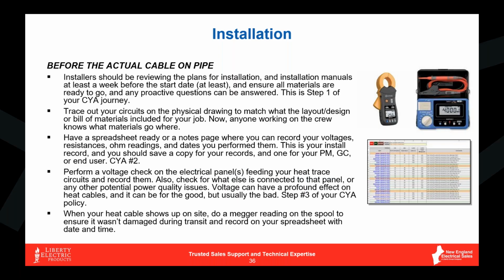You definitely want to have a record sheet because you're going to want to test voltage. You're going to want to know what that incoming voltage is before you even begin putting heat trace cable on the pipes or putting the controls on the wall. We've seen this happen before where we're told that the stated voltage is say 208, the cable doesn't perform well, a lot of complaints start happening, and then we go out there, put a meter on the incoming voltage and find out it's 198, which is going to make a big difference on the heat output of that cable.